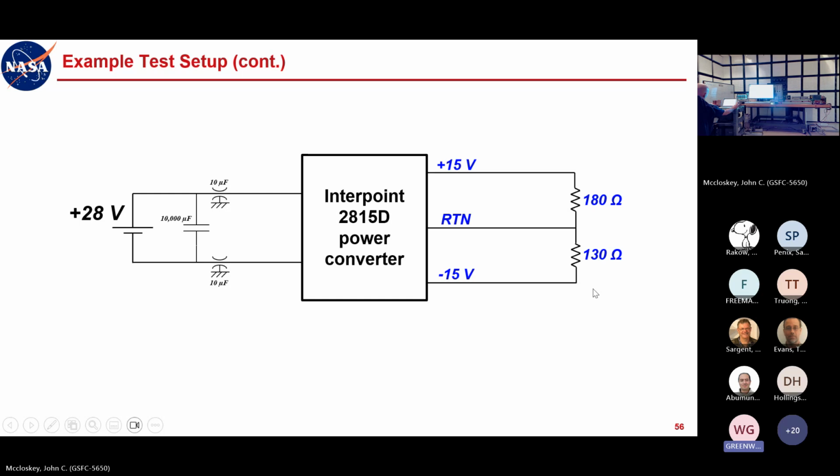It's the noise generated in this converter, generating the common mode. They're moving in the same direction on the positive, and in the same direction on the negative voltage, and they should intentionally return back on the return, right? And it's doing it. But that common mode current, because it's returning on an impedance that's higher, at least, than on the positive or on the negative, you have a mode conversion there.